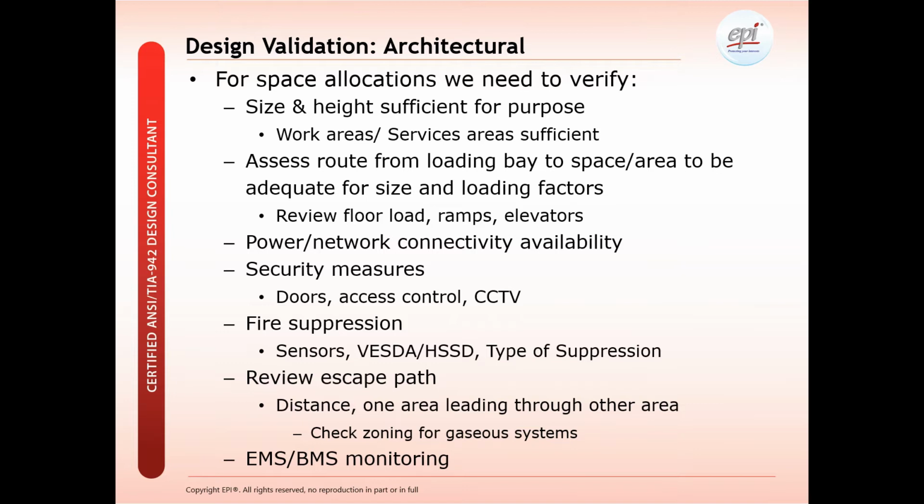We'll also review escape paths to make sure we're compliant with local regulations for safety, as well as look at how to properly design so that we can maximize spaces and separate the disciplines to ensure high availability. We'll also consider zoning for fire protection in consideration of the TIA standard, as well as the authority having jurisdiction or your local fire codes.